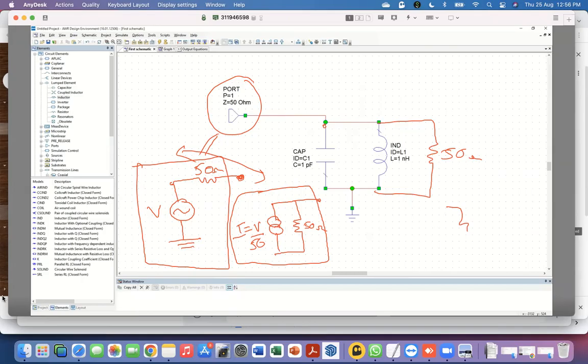What is the equivalent of that? That you connected a multimeter across a device, and you ideally in those circumstances don't want the multimeter to change anything about your circuit, right? You don't want to introduce any impedance across it. So that's why an ideal voltmeter has infinite impedance. Of course, in reality, no voltmeter is that ideal that it has infinite impedance, but it's high enough in the context of the circuit that it doesn't matter. The errors are very small. This is impossible to do in microwave, or nearly impossible in most circumstances. And this is one of the points we'll be discussing later.